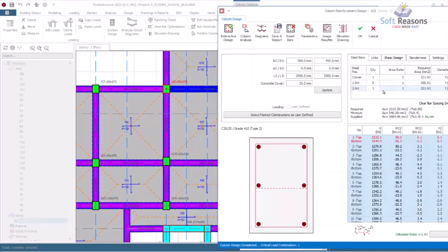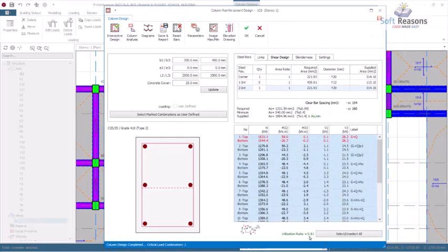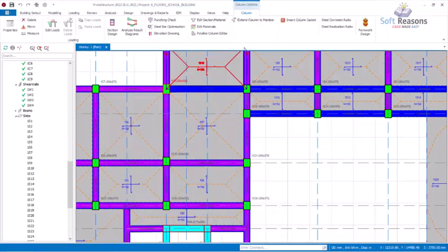Click on the OK option, and then if you check the U ratio here, you see 0.81, which is not bad. This column is not going to crack because it is not very close to 1. It is not too close to 1, before you now get to 1. So this is a good design successfully. These are the points you are going to be checking. The U ratio is very important. I click on the OK option and then I click on OK to have this applied successfully.